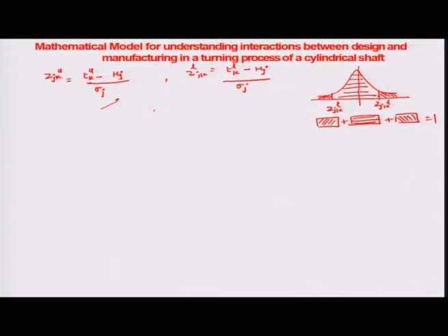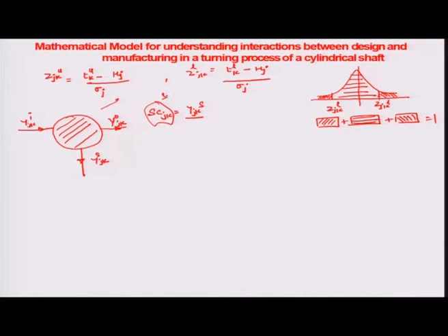So, in context of that, we had also recorded that the total fraction of the scrap of the kth specification to be machined on the jth machine would be found out as the ratio of the total number of scrap coming out of the transformation process, given a certain input level. Let us say there are exactly yi components coming into the transformation process which would obey the kth specification developed on the jth machine, ys jk coming out as scrap, and similarly yo jk coming out as the output. Obviously, this scrap fraction sc jk can be a ratio between the scrap and the input, that is ys jk by yi jk. And this was represented through what are the process rejects.